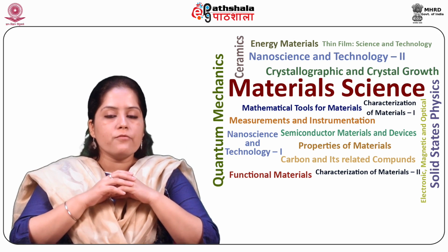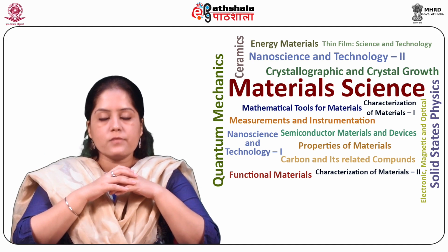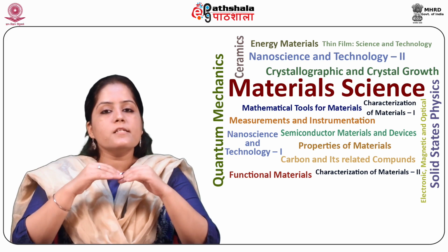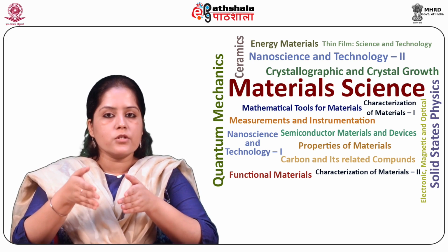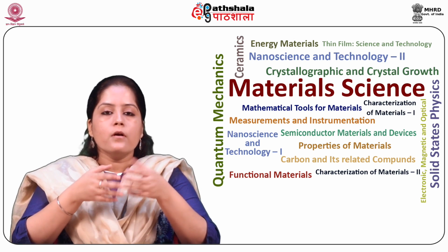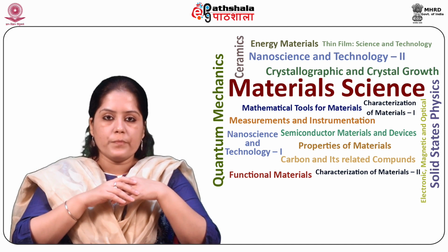Third, the silicon wafer is cleaned and kept in a thermal furnace which can go up to a temperature as high as 1500 degrees Celsius. Next, this oxidation furnace is subjected to either dry oxygen, that is dry thermal oxidation, or water molecules, wet thermal oxidation. The molecules of oxygen or water react with the silicon surface, forming a thin oxide layer gradually.